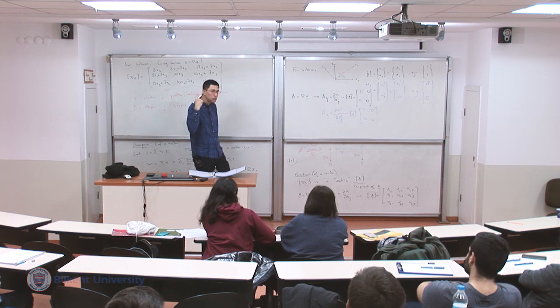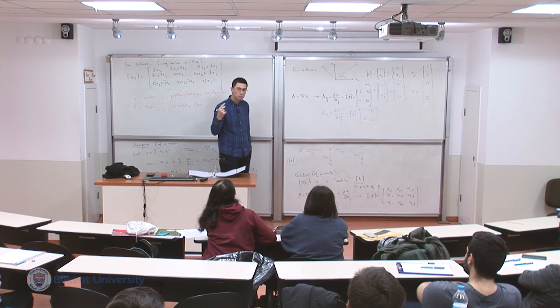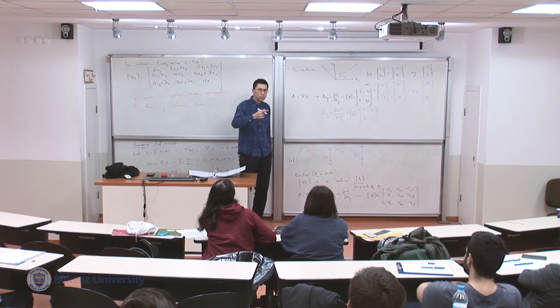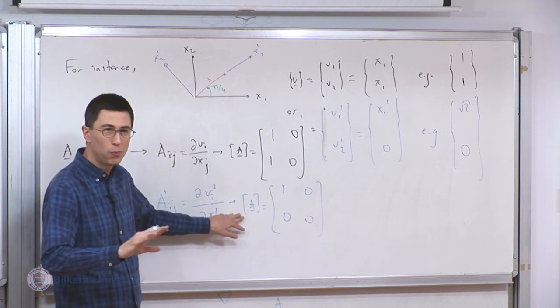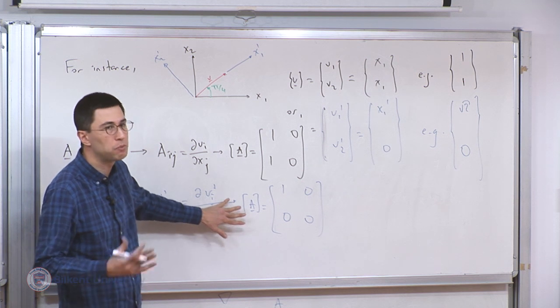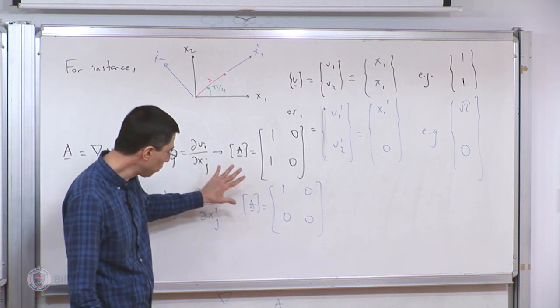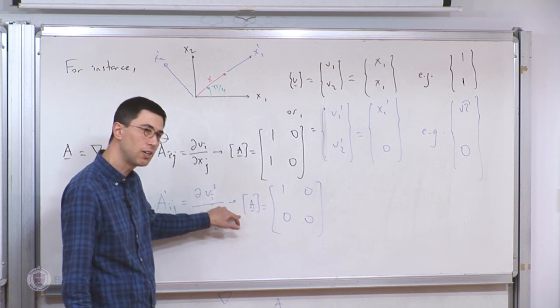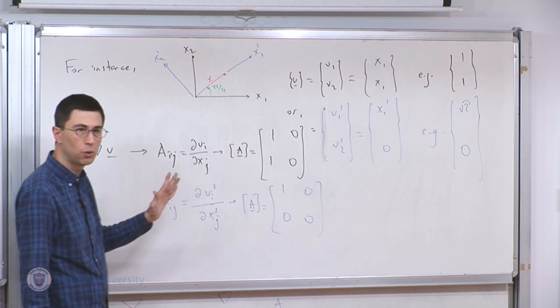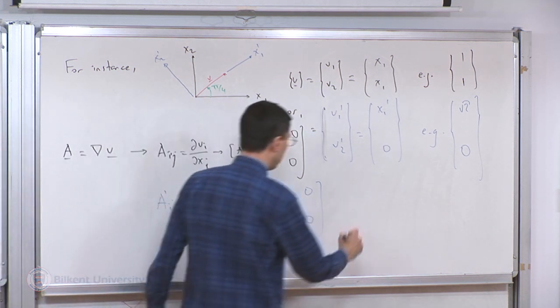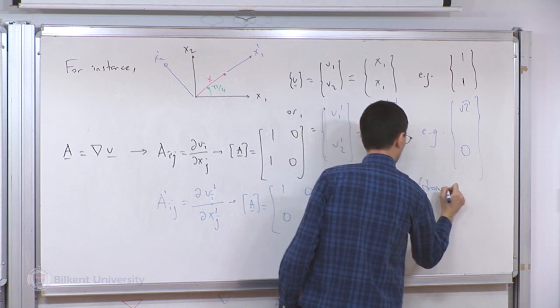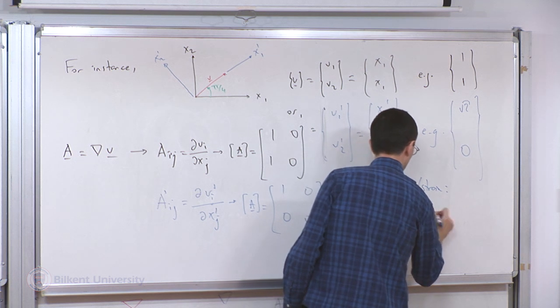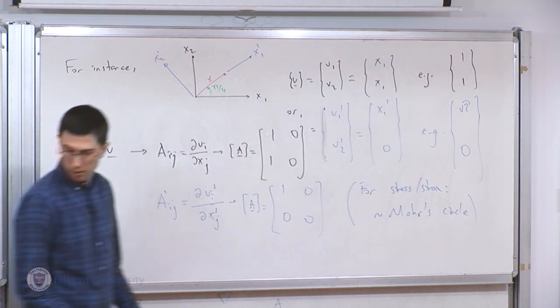And this concept is not something that you are foreign to. Remember the Mohr circle? In the Mohr circle, you change the directions, and when you change the directions, you calculate new components of the stress. We don't teach you this view because it's perhaps too impractical, too mathematical. But what you're really doing is calculating the components of the stress with respect to a rotated axis. So this is intimately related to the Mohr circle, for stress and strain.